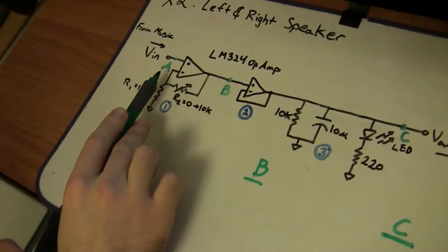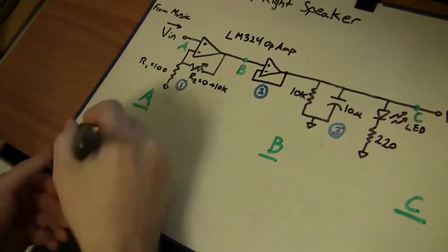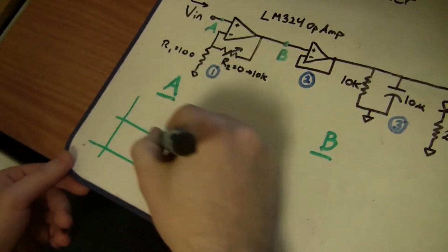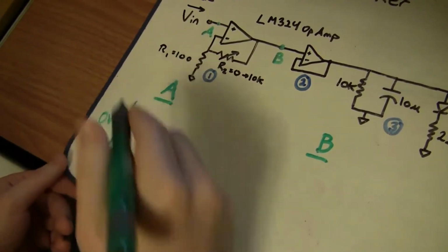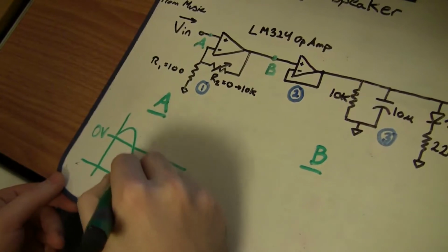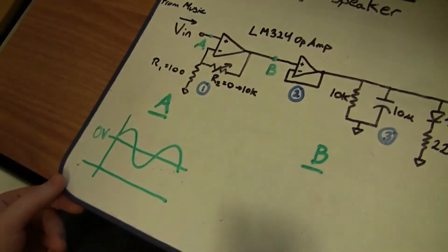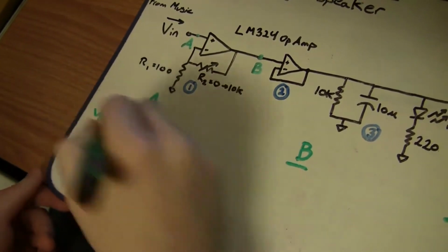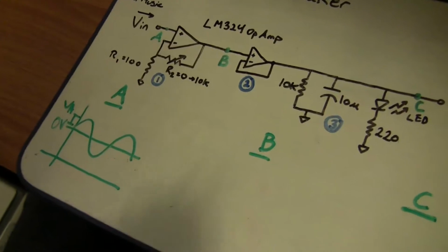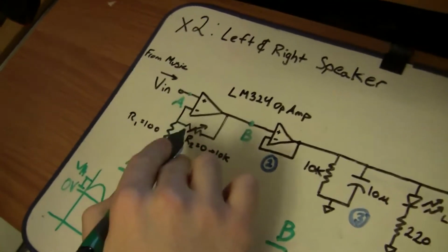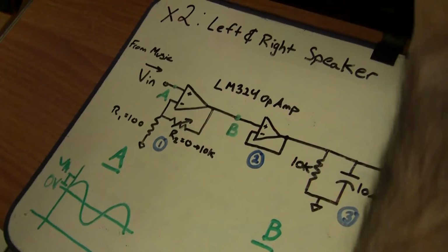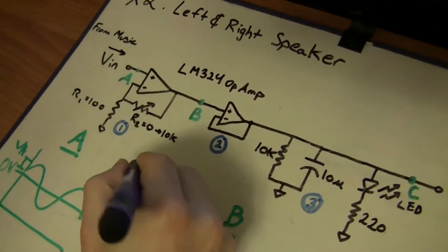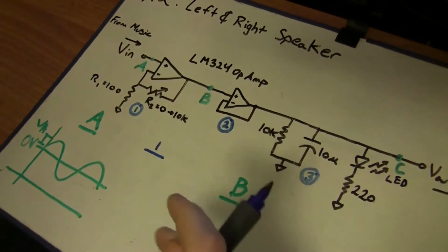So first we start here at the input. The input has a very weak signal based around 0 volts. So the signal itself goes both positive and negative with a small amplitude, VA. So this then is fed through a non-inverting op amp, which is governed by a set of equations which I'll specify from here at 1.